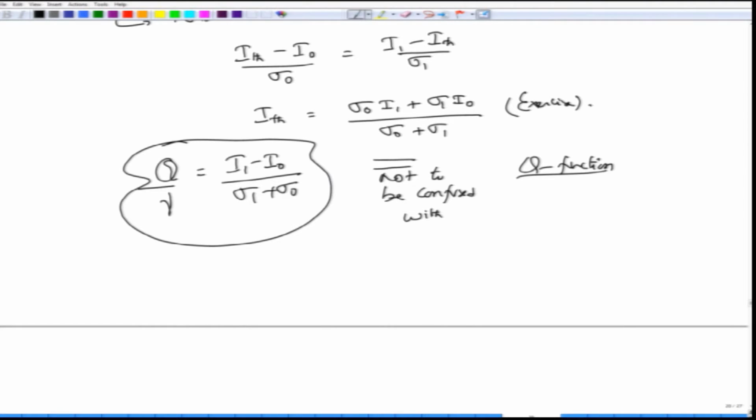This is what determines what would go into the probability of error, and this factor will be different for different receivers. For the pin receiver, suppose you want to obtain, let us say, a BER of 10 to the power minus 9. This means that in the expression for the probability of error, after you have chosen the optimum value of the threshold correctly, you need to have a certain value of gamma such that Q of gamma is the bit error rate, or the probability of error.